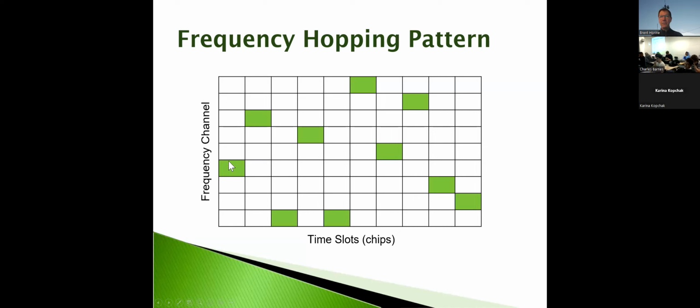In an FSK system, you might have some deviation here that represents one frequency might be one symbol, another frequency would represent another symbol. That could be within this slot if these slots are pretty coarse, or it could actually be just multiple slots. But most likely you're going to be doing it within this so that we can have other types of sequences, hopping patterns that would be orthogonal to this one, right?